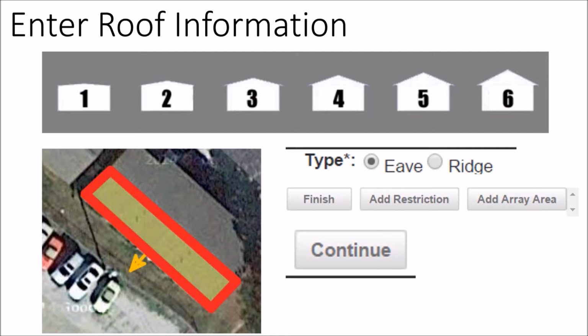You may not have that LiDAR data. You may need to guess at the roof type, but to be perfectly honest, there's not that much dimensional difference between a 4/12 roof and a 5/12 roof. So if you're close enough and you're leaving those offset distances anyway, then you're really not in that much trouble if you are off by one roof tilt angle size.